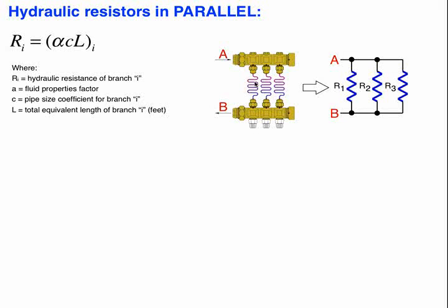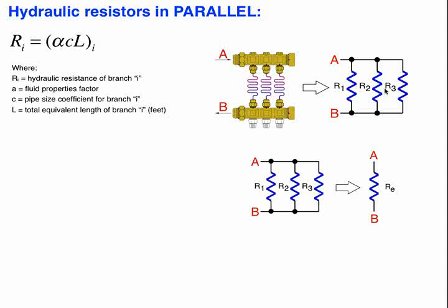Well, just intuition tells you that a 100-foot circuit has less resistance than a 200-foot circuit, and so forth. But we can represent these three circuits by these three resistors. All right, and then we can combine the three resistors, which we now say are in parallel, into a single equivalent resistor. Again, if you've ever done an electrical course, you've probably done this.